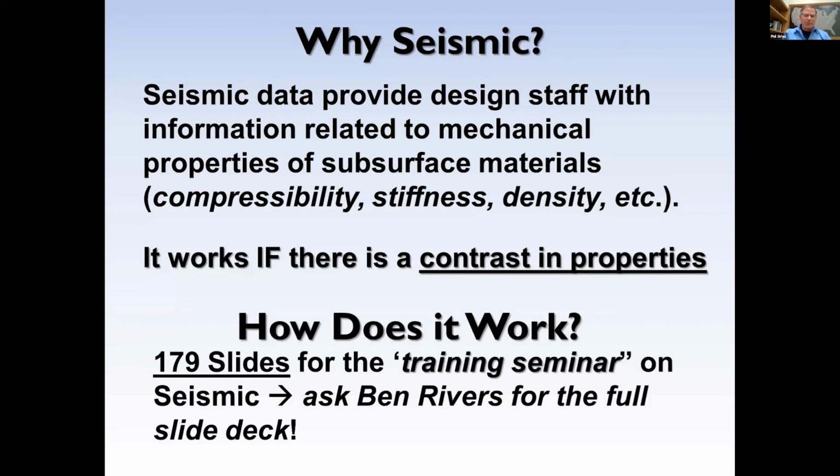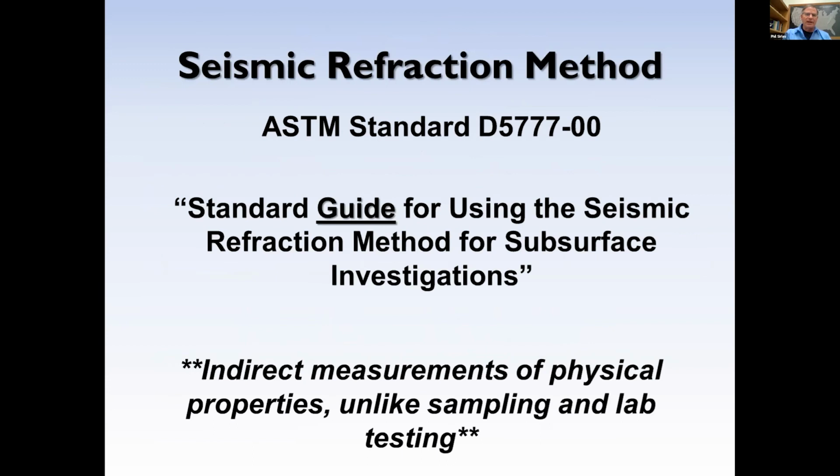So today, I have about 25 minutes to share with you, and that comes from a 179 slide deck from a training seminar that was put on by Central Federal Lands, and Ben Rivers has that if you'd like. These are just a culled down set of slides from that. The seismic refraction method does have an ASTM standard, as do many geophysical methods now. I believe that's overlooked. They aren't standards in the way an Atterberg limit is. They're guides. I wouldn't want anybody telling me all my geophones need to be spaced at 10 feet, but at least you can have your consultants or anybody else you're working with work under these guidelines and make sure they're doing it.